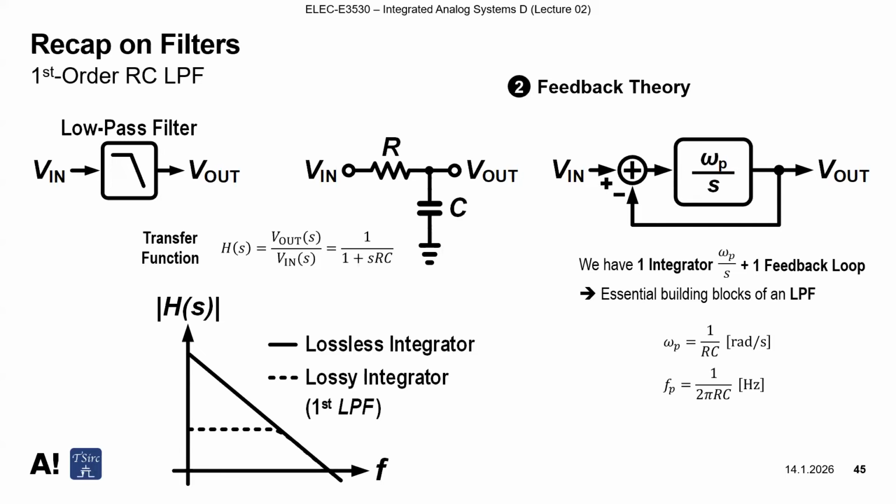When we plug in, as we did for the intuitive analysis, for DC, s equal to 0, then it goes to infinity, right? For the ideal case, it just blows up when we go to DC. This is also very easily predictable. When we build the ideal integrator, it will just accumulate inputs forever, so it will end up blowing up. So it matches our intuition.